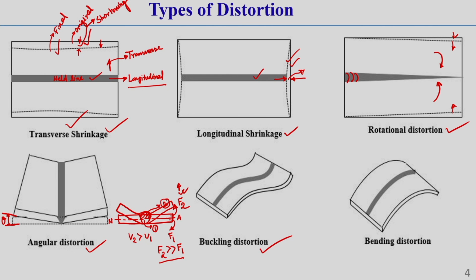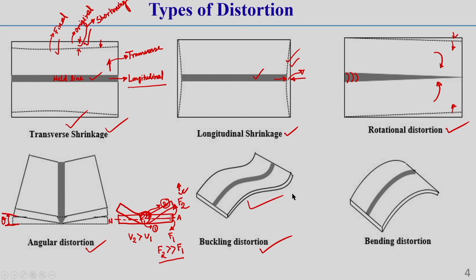That means the buckling phenomenon, you are well familiar with this, because during shrinkage time some sort of shrinkage force occurs. Due to this shrinkage force there is a chance of longitudinal shrinkage. Understand, due to this longitudinal shrinkage, and due to the thin section and the lower critical length and higher critical length of this plate weld length, there can be a chance of buckling of this thin sheet or thin plate. So buckling means it fails due to this shrinkage effect, especially the longitudinal shrinkage effect.